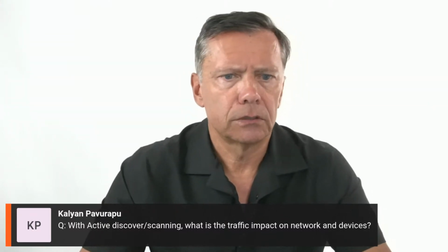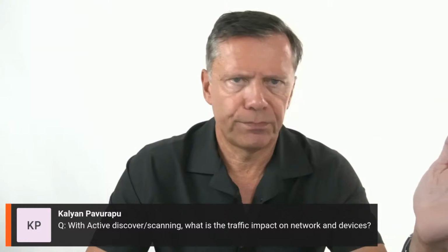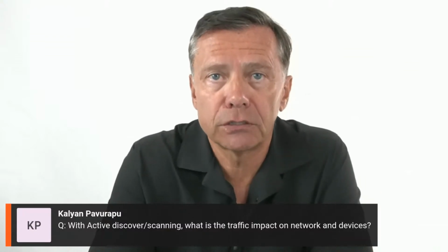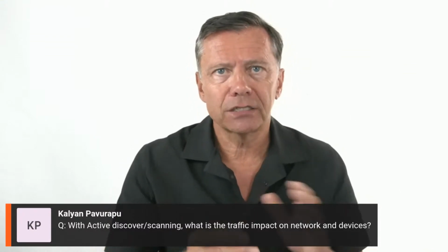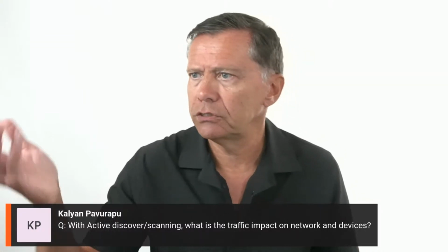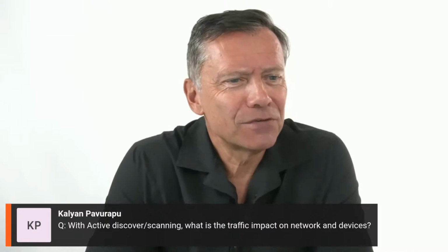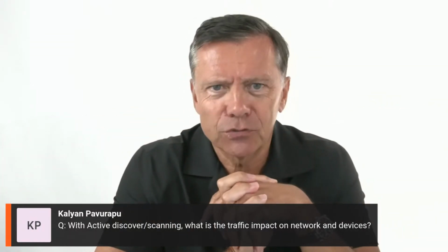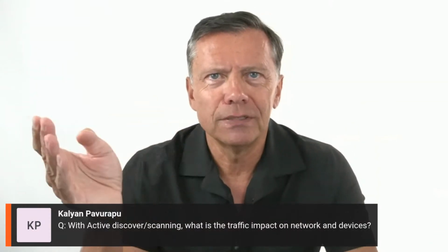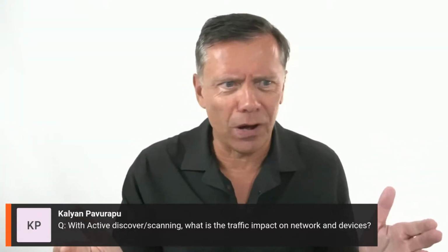Your average vulnerability scanner will bombard the endpoints with tons of packets, okay? Because they're just trying to figure anything out. And this is commonplace in IT, it doesn't work in OT. So the active discovery that is implemented in OTbase, you can compare that to RSLinx, for example, or to Siemens TIA Portal. So they also do active discovery, shocker. And if you would examine the network traffic in Wireshark as an example, you will see the exact interactions that happen, and you will see, oh, wait a second, that was just a couple of seconds, and now I have all the details. Wow, how did that happen?